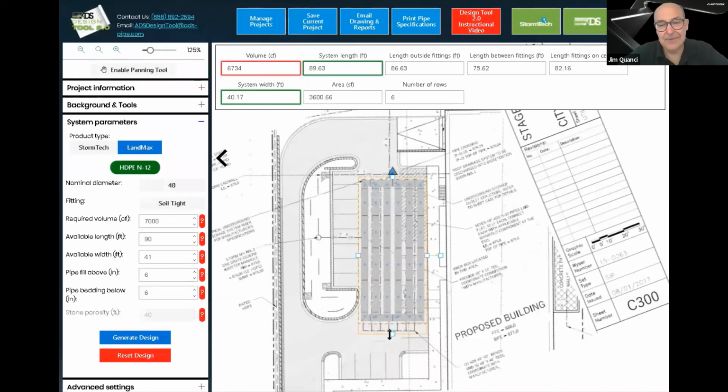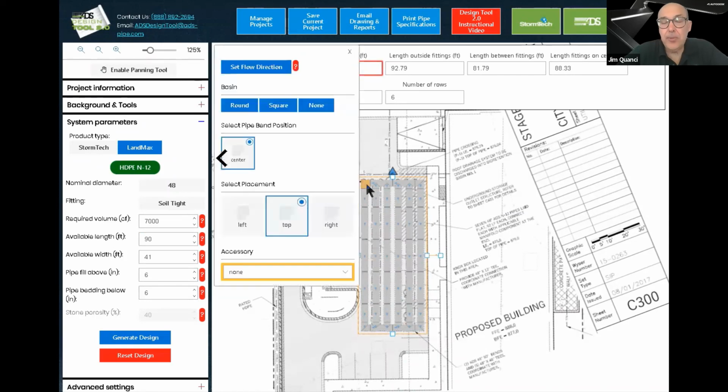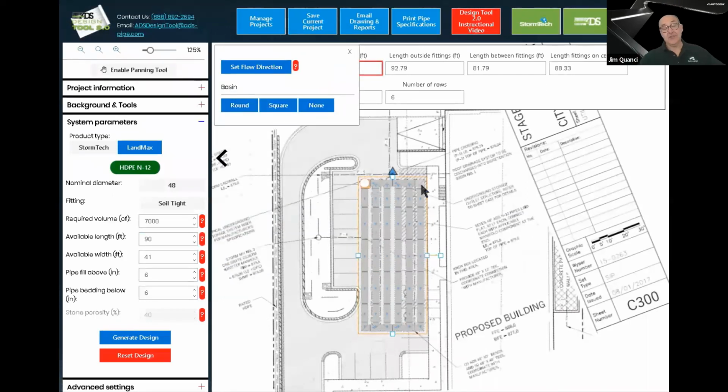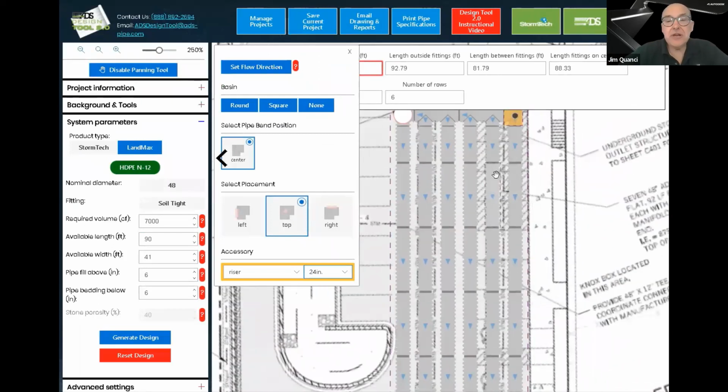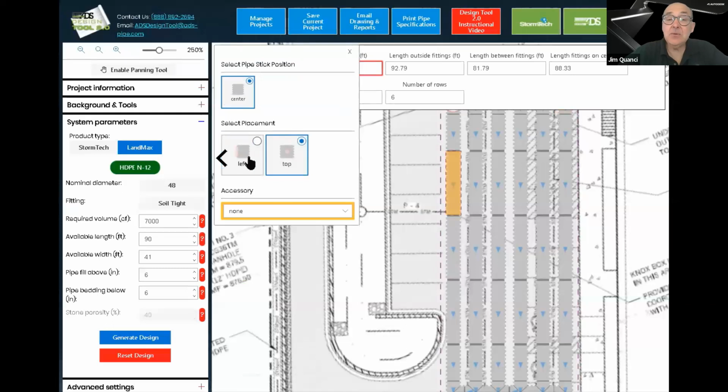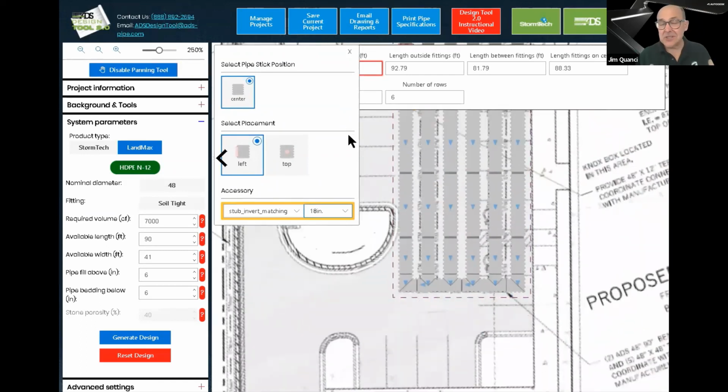It's a drainage system that is under a parking lot. Because when you build a parking lot, you've got all this water that's running off the parking lot that can't go into the soil because you've got asphalt down. So you need to put in a drainage system. Where's all this water going to go? And this configurator was built for Advanced Drainage Systems. And at the end of the day, what does ADS want? Along with giving their customer confidence in a design, and the customer is typically a civil engineer. So this is a pretty sophisticated customer, somebody who's used to doing all of this using Excel spreadsheets and a lot of handwork over several hours, and can now do this quickly and easily on a web page.